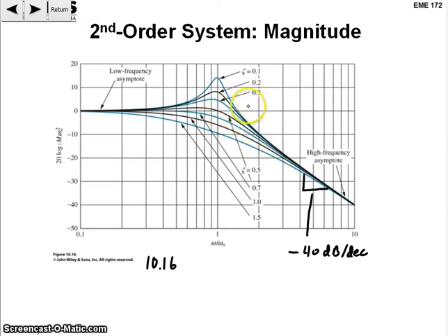If this is an actuator, if we're applying a force and we want it to move, we need a lot of force to move where we are above the resonant frequency, and proportionately less force elsewhere. So we can move our mass very accurately down here, but up where we're down by minus 20 dB, we need 10 times the input force to move this thing. At minus 40 dB, we need 100 times the input force, and we probably don't have an electromagnetic actuator that can do that.